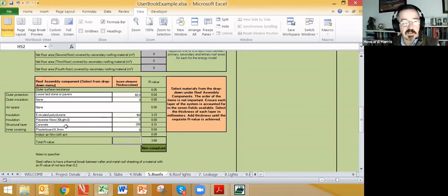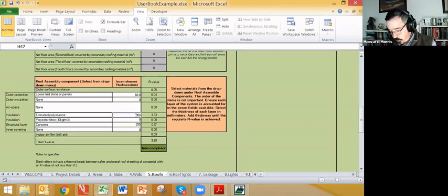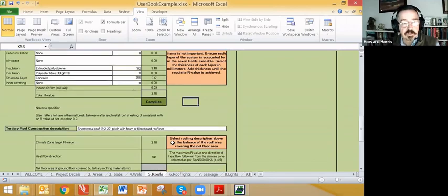We wouldn't quite get there unless our concrete slab was fairly substantial, a 255 millimeter slab. If not, we'd have to boost the insulation level slightly. Of course, we wouldn't have any plasterboard in all likelihood, so we would need to zero out the plasterboard, and that means that we're probably back at slightly over 100 millimeters of insulation to get to where we need to be.